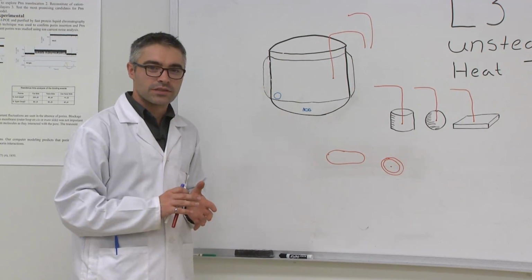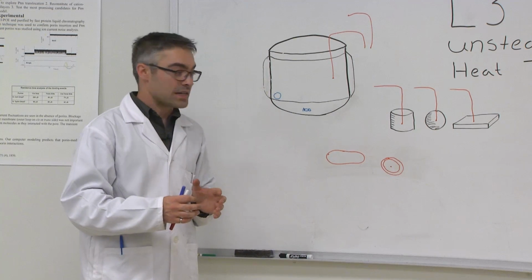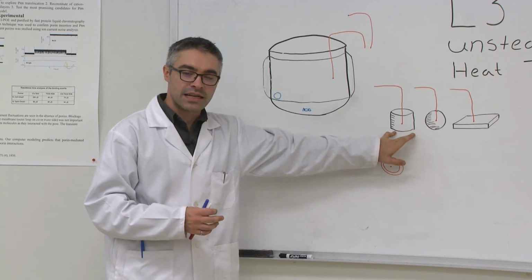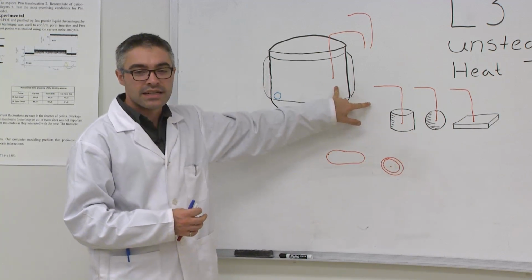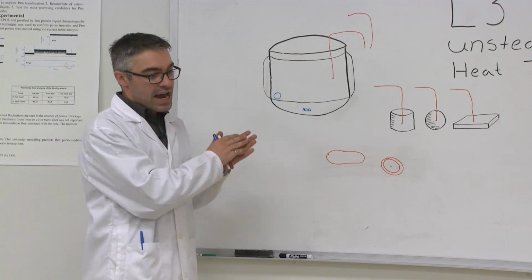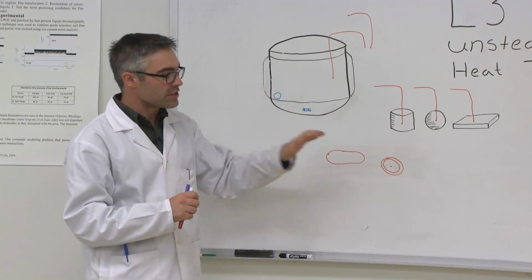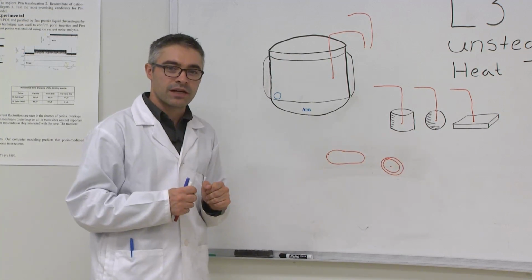In conclusion, you will use the 3 equations given to you in the manual to determine, with the characteristic distances measured in the laboratory, the delta T measured from the beginning of the experiment until the end, and you'll determine theoretically how the heat should be penetrating according to theory. You'll then compare your experimental data to these theoretical applications and look for any discrepancies therein.